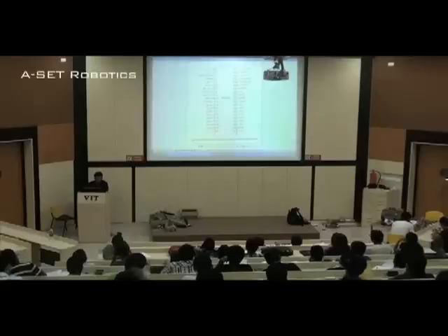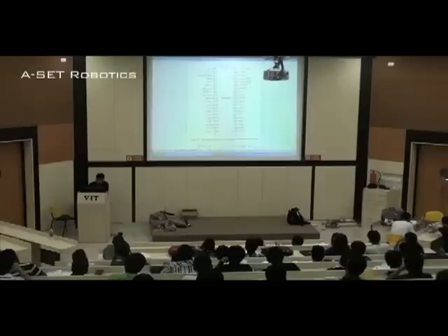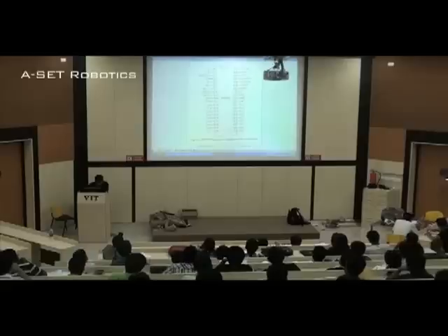Now we will be going pin-wise, but one thing that I need to tell you is that you can see AD0 to AD7. Can you see it? These have arrows at the back and arrows at the front, whereas INTR has an arrow towards the microprocessor and INTA has an arrow going outside the microprocessor, right?